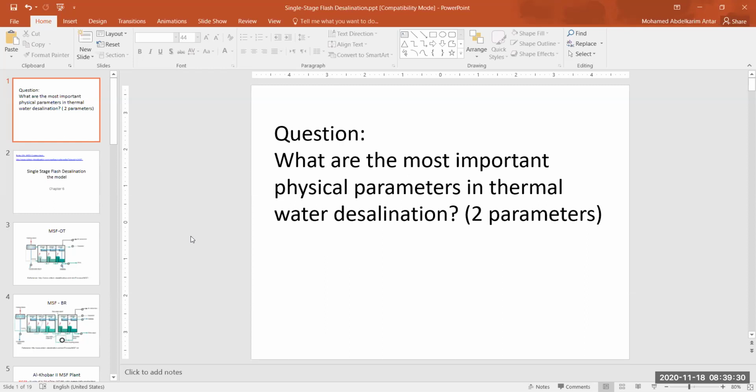In the multi-effect desalination system, as you are moving from one effect to the next one, the pressure reduces, and that's why the corresponding saturation temperature drops, so that the vapor that's coming from the previous effect, when it condenses, gives the latent heat, and at a lower pressure and lower saturation temperature, it is going to generate an additional amount of vapor and so on.